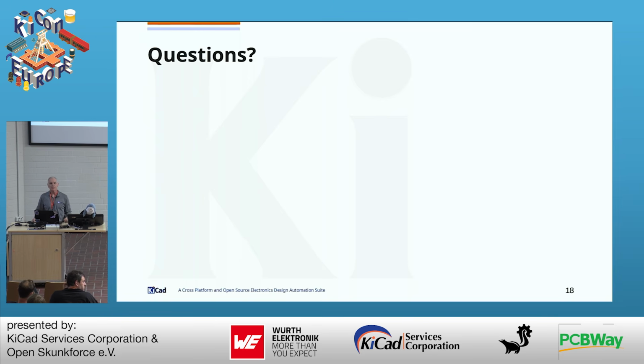Okay, so if there are variants that have 2 footprints, I can decide between 2 footprints for the same symbol. I have both footprints in my PCB layout, and I can decide by myself if I want to overlap them or have them side by side. Yes, you can lay them out and orient them. They have to be 1 to 1 and match the symbol, because otherwise you wouldn't be able to create a netlist.